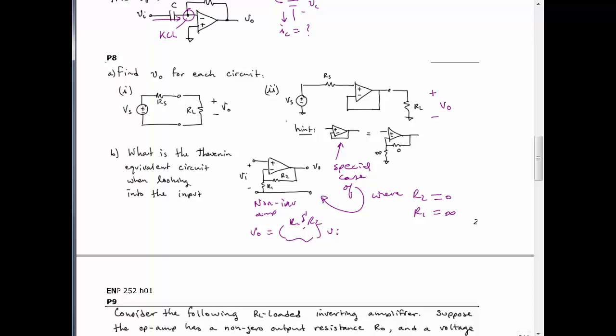Whenever you have some source signal, it could be a microphone, could be the output of some amplifier, and you're trying to transmit a signal down a transmission line over a distance, you can model that in the most simple form as a voltage source and then a series resistance, RS. At the other end, where you're going to make use of that, you'll have some kind of input resistance to whatever that Thevenin equivalent would be of the network that you're connecting to. And that network receives the signal and is going to do something with it.